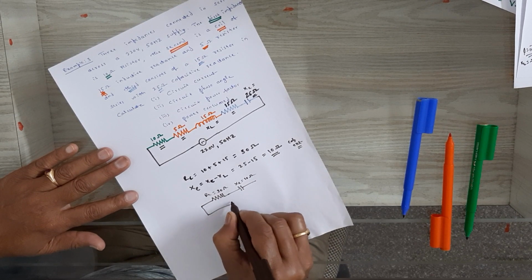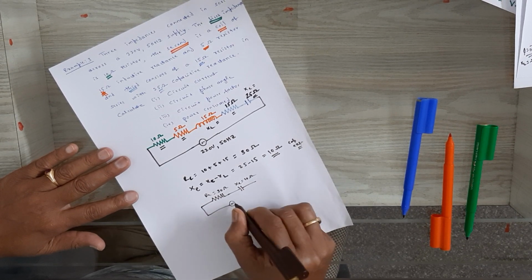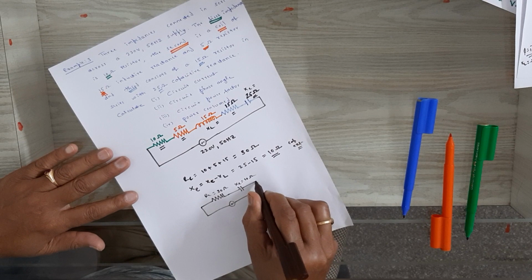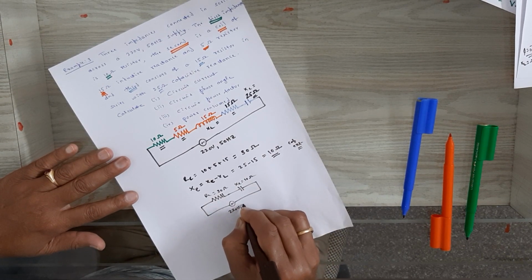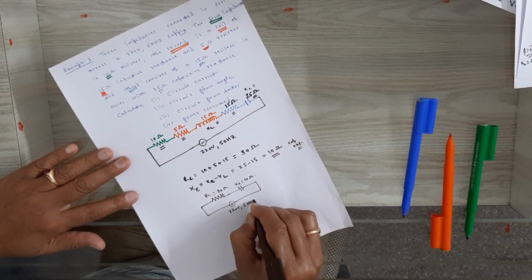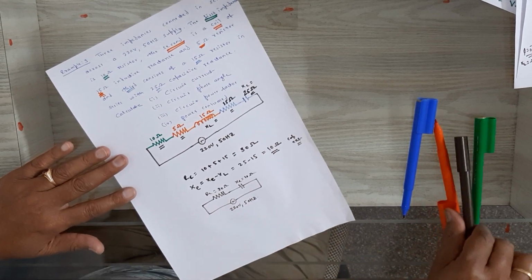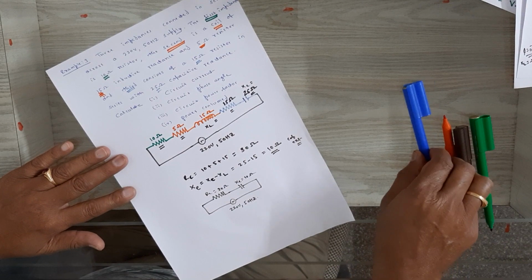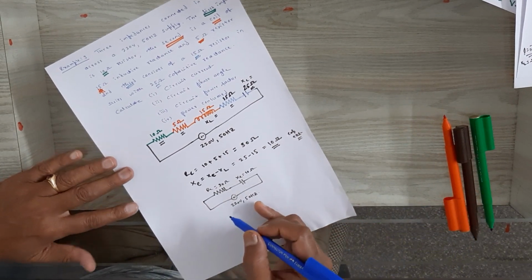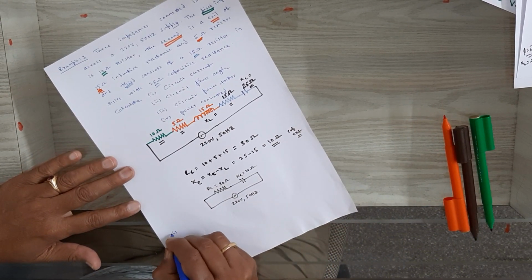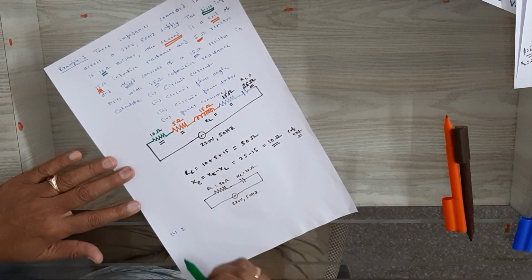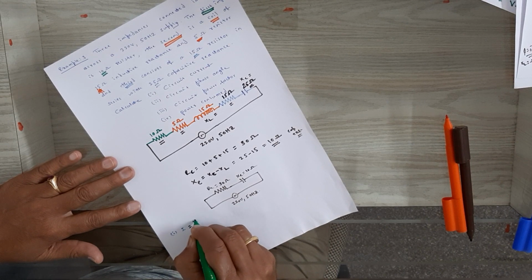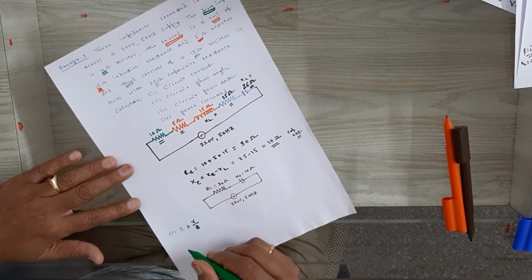Then the same voltage is applied here, 220 volts and 50 hertz. Then calculating the current is very simple. The first thing you have to calculate is I, that is, I is equal to V by Z. Here we have to find out Z.